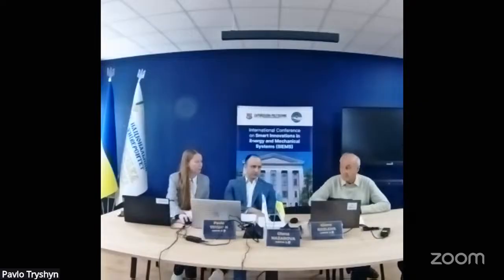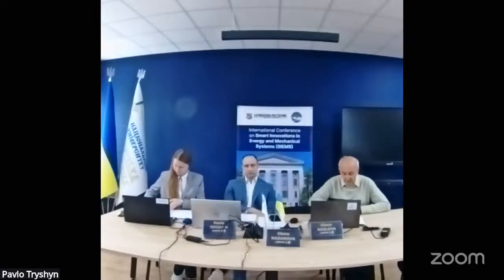Yes, one more question. Olga, please explain what factors make it possible to increase the efficiency of a dual system wind turbine. The efficiency of a dual system wind turbine is increased because the major part of wind flow power is conveyed by the subsystem with aerodynamic multiplication, a generator without a frequency converter, which has maximum efficiency.